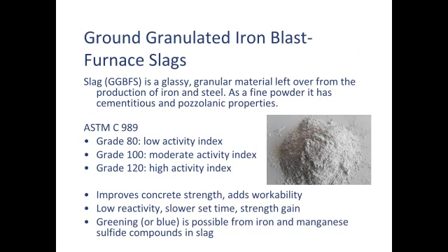And then another pozzolan that's a pure waste product is called slag. It's technically called ground granulated blast furnace slag, or GGBFS, and it comes from the refining of steel and iron. So when they're melting steel, or they're taking raw iron and turning it into steel, they have to control the oxidation of it. They put in limestone, and they put in some other kinds of minerals that act as a flux. So this rock melts on top of the big kettle of molten steel, and not only does it block the oxygen from getting to the steel and causing it to oxidize, but it also acts as a sponge to help suck impurities out of the steel.